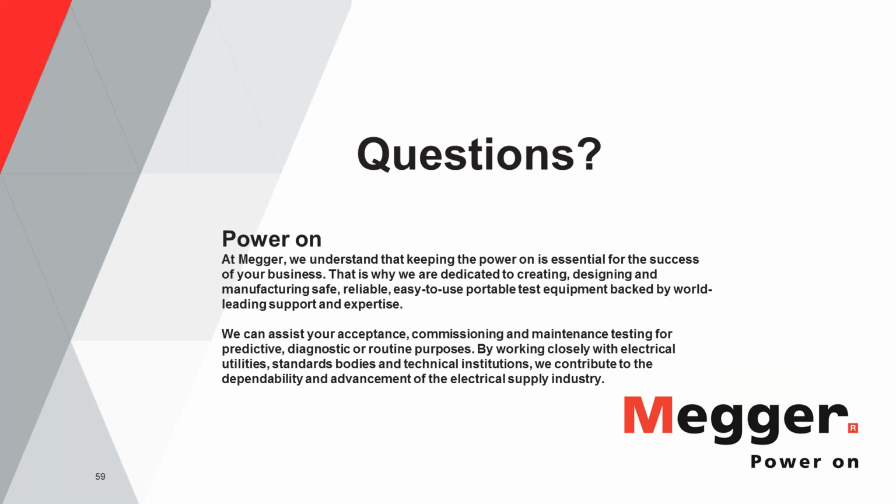Okay. Next question is, can the MS2A be used for ground fault testing? So this is related to the previous one. The NEC, National Electric Code, Article 230.95 says that the maximum pickup value that can be set on the ground fault is 1200 amps. So if you go with either 1.5 times or 2.5 times that, you get the maximum test current that you need to inject during the ground fault test.